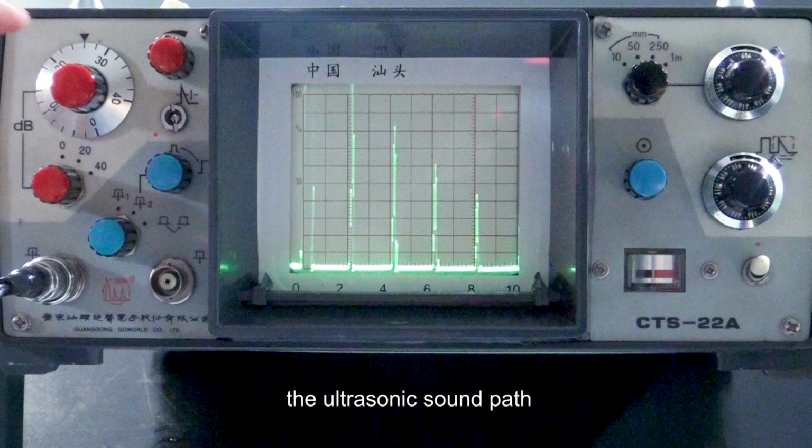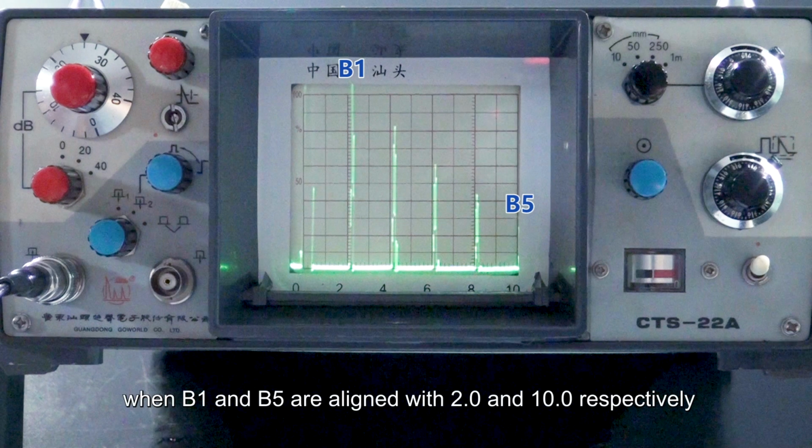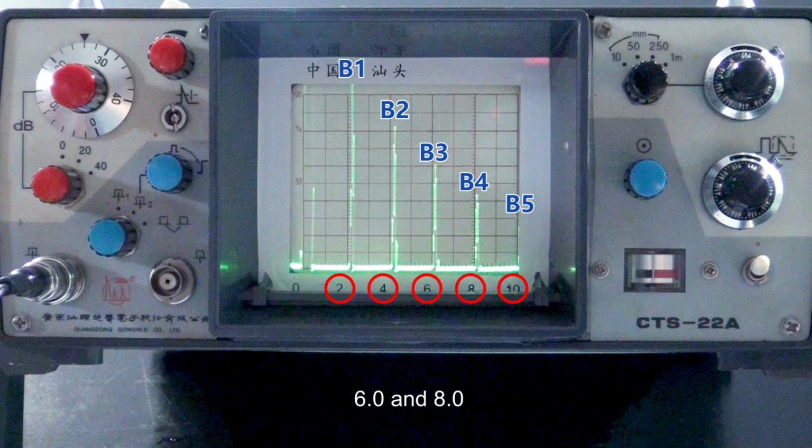Theoretically, the ultrasonic sound paths have equal differences between two bottom waves. Therefore, when B1 and B5 are aligned with 2.0 and 10.0 respectively, B2, B3, and B4 should be aligned with the horizontal scales 4.0, 6.0, and 8.0.